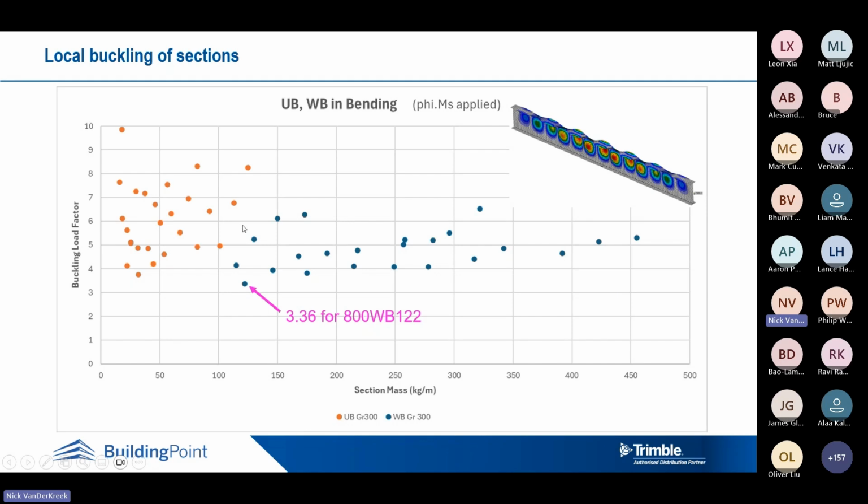So that is the ratio of the design section capacity in bending to the elastic buckling load, the bending moment associated with that. It seems like the webs play a big part in even the bending buckling mode, but the plate and the web, of course, are an assembly and they're buckled together.